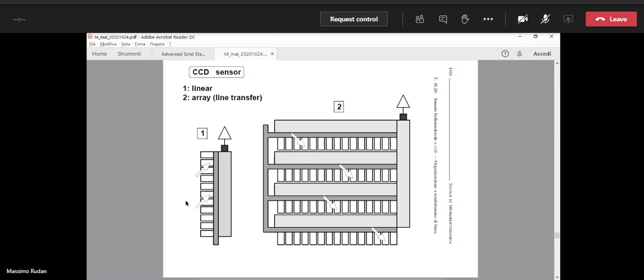So the photocapacitors integrate the charge corresponding to the optical signal. And then you see the gray strip, the thin gray strip that is placed vertically immediately on the right of the photocapacitors. That is a gate. By operating this gate, one can transfer the charge that has been integrated inside each photocapacitor from left to right into the vertical CCD.